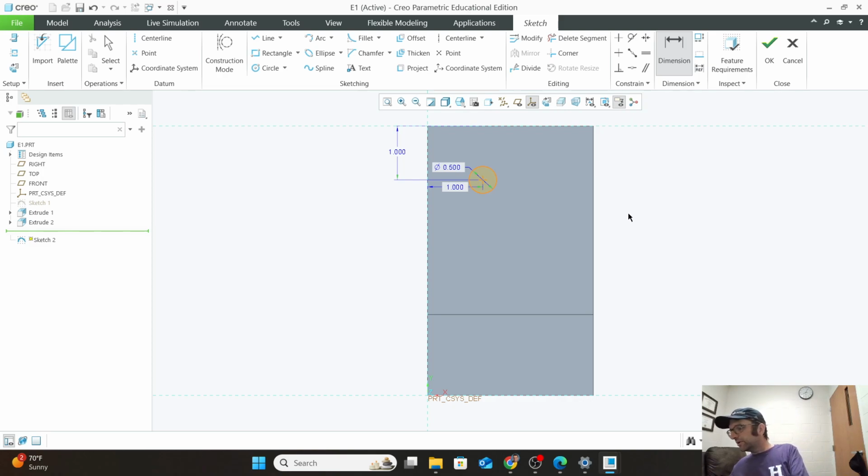And we're going to go ahead and put that hole into things. And then I'm looking at it. Oh, my dimensions are right on there. Scale looks a little bit weird. Is my hole too small? I almost feel like it is. Yeah, it is. So this hole doesn't look quite right. It should be 3/4 of an inch in size. So let's go back to that and edit that dimension, 0.75. Hit enter. Now we're looking a little bit better.